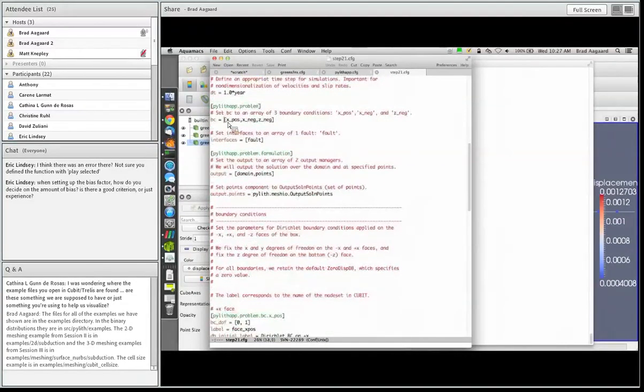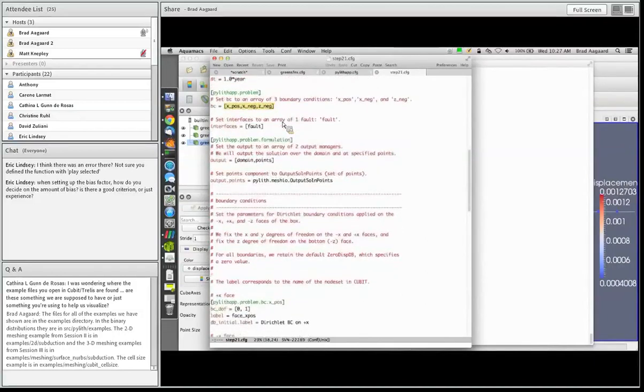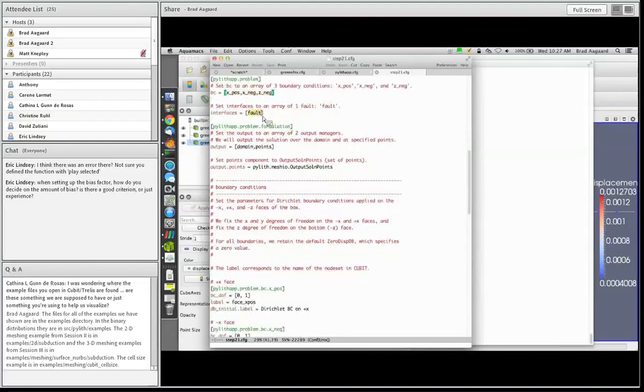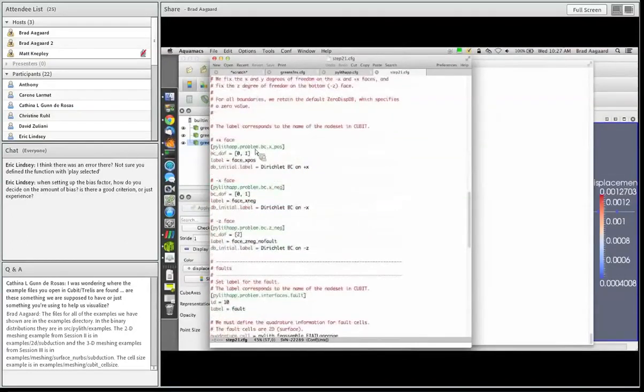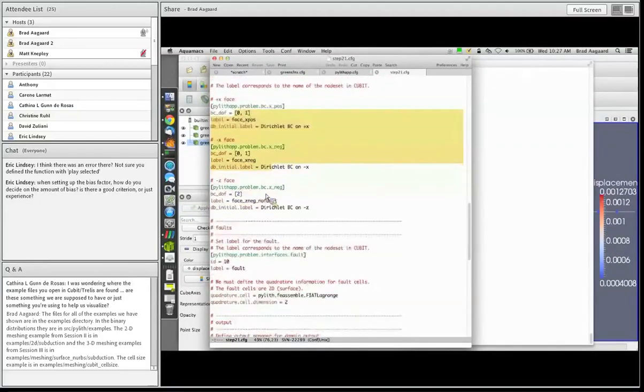Output, we'll use HDF5 output. Our domain, as usual, is step21.h5. Our points, we add dash points. We put our points for our Green's functions in this file, greens_functions_points.txt. Here we're going to use a space dimension of 3. That's our coordinate system for that points file. And the units for the vertices are going to be in meters rather than kilometers like we've used in the past.